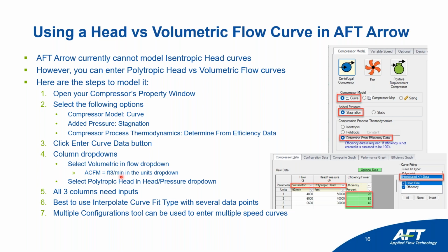We like to represent that as this feet cubed per minute term, so if you're having trouble finding it, that's why. And our polytropic head, we have it in feet or meter units, as well as other length units. So that's our options. You would have to convert from energy units to put it in if your curve is in energy units currently.